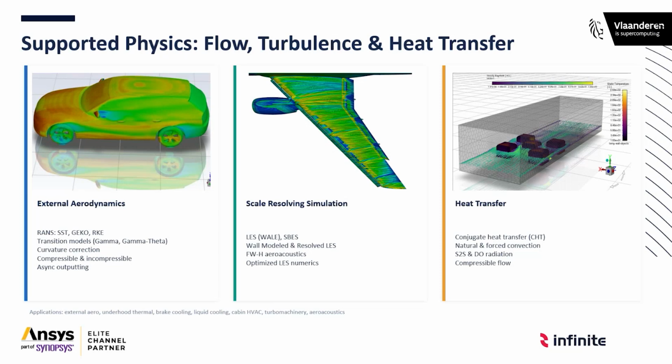We can run a large eddy simulation, stress blended eddy simulation, include wall modeling or resolved LES, and year by year the numerics are increased. Important to mention is the increasing CFD speeds achieved with these GPUs enable customers to start looking at scale resolving simulations, while in the past this was only possible in small cases for academics.